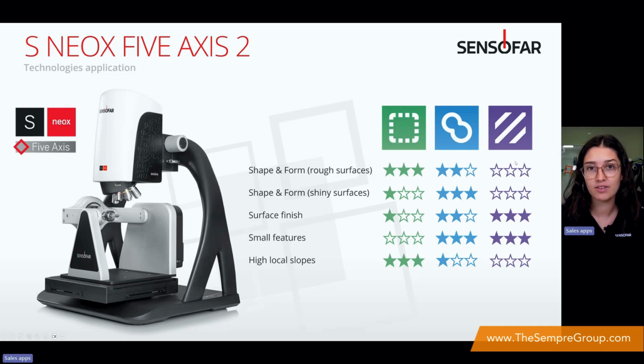And finally, we have interferometry in purple. With this technique, first of all, this is the one that has the best vertical resolution of all. And again, that's why it's the best one to measure small features, in this case in the Z scale, and also to quantify surface finish.